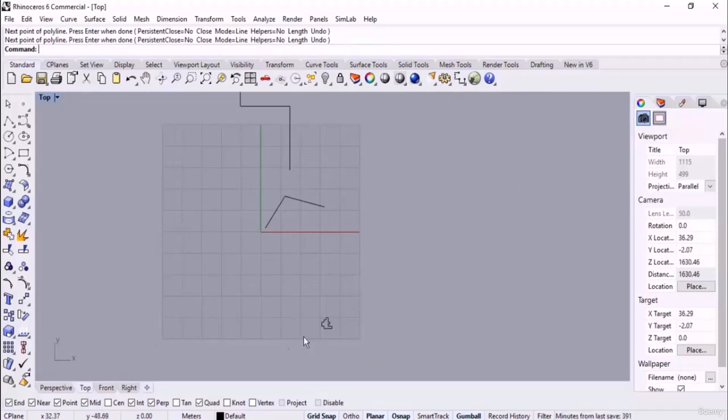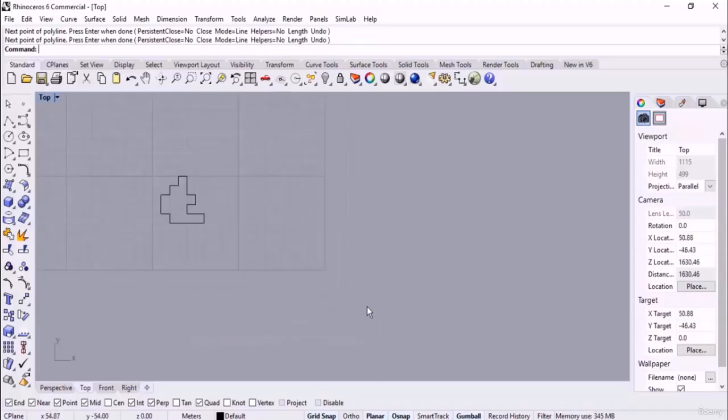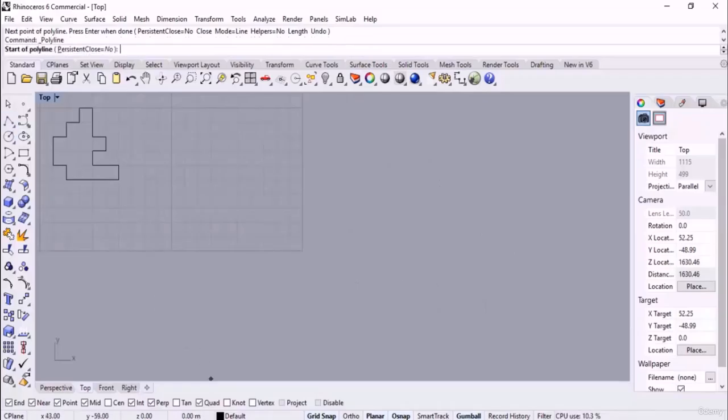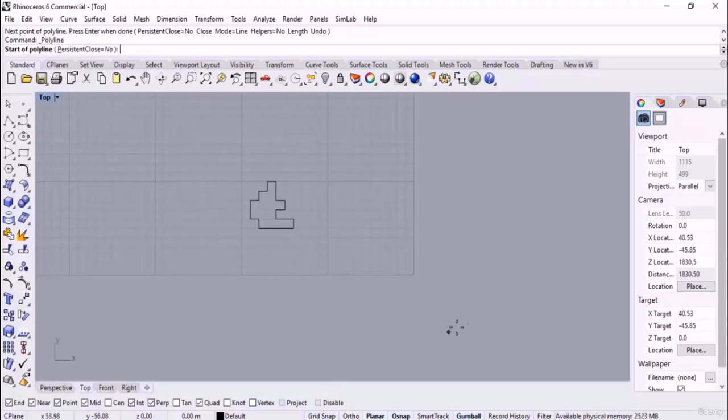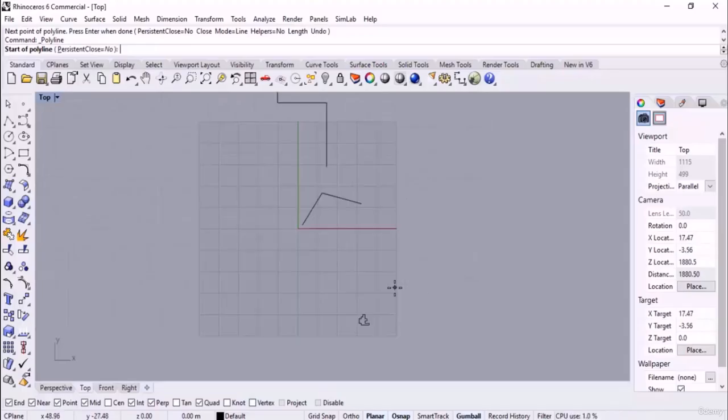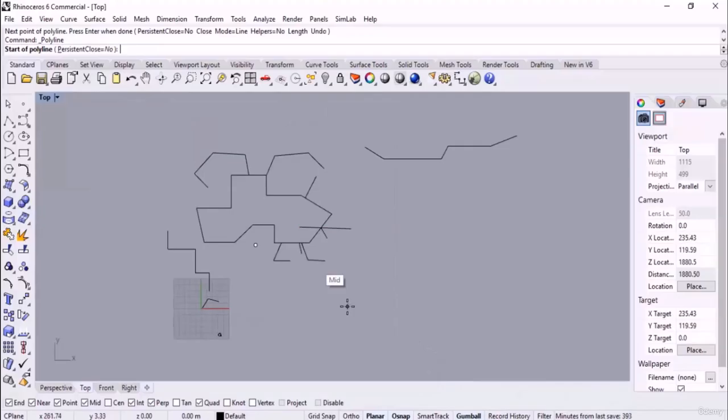What about the points? As I told you before, we got an infinite array of lines here, which are endless. However, only a defined region of it is visible in the viewport. We got the grid lines everywhere in the viewport, but graphically it is not visible. We can extend the visible region of the grid lines, but it is not necessary. So even when the grid lines are not visible in the viewport, we should know that it covers the whole viewport and the plane is infinite, and we can deactivate it if we don't want to constrain the marker to the crossing points.